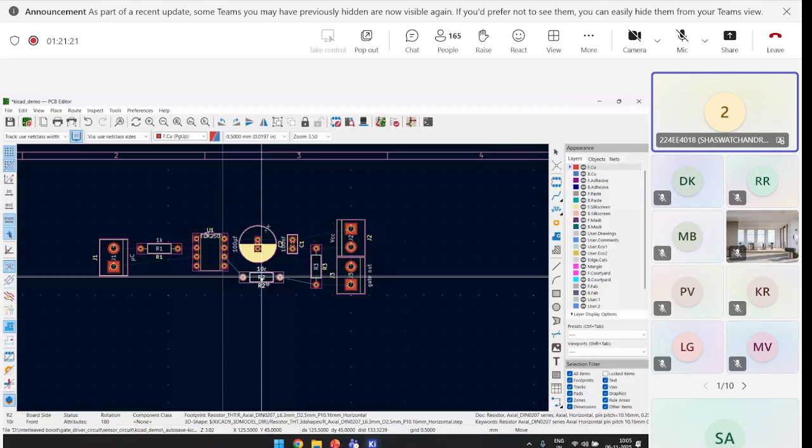So here you can see there is FCU and BCU. FCU stands for front copper and BCU stands for back copper. We'll be using this because in this specific case, for this gate driver circuit, it is a single layer PCB, so we don't really need it. We can use either of them. For more complicated circuits, in order to tell the PCB manufacturer that this side is front copper and this side is back copper, we will be using different copper for different purposes, right? But in this case, as it is single layer, we can use any of these. So I'll be using this back copper.